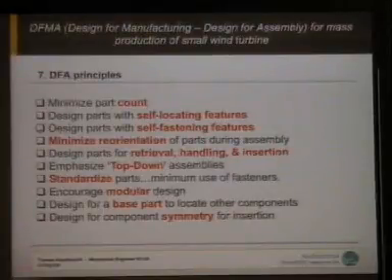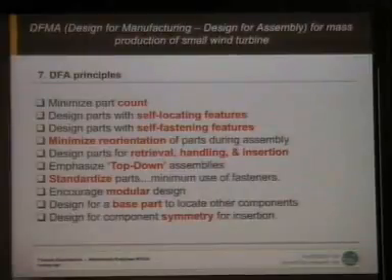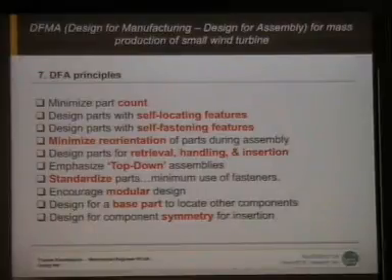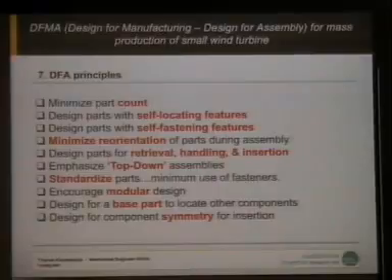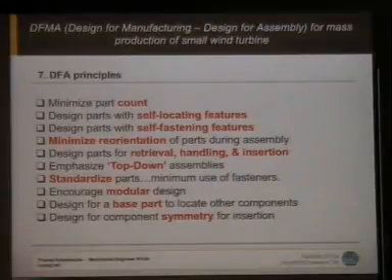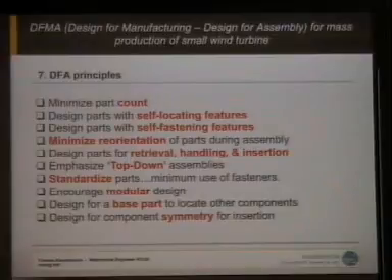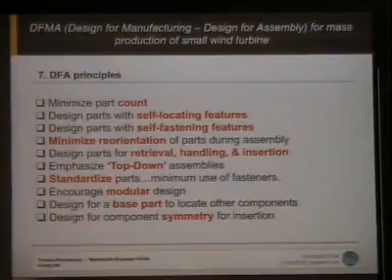You have to minimize the part count and design parts with self-locating features so that you don't get confused when you assemble each part. It has to be very easy to assemble. Minimize reorientation of parts during assembly. You have to have a certain orientation for all parts. Design parts for retrieval, handling, and insertion.